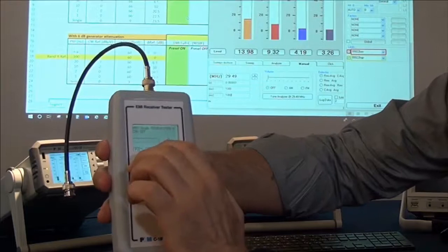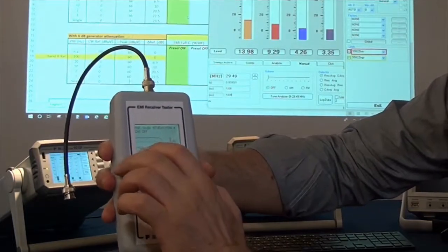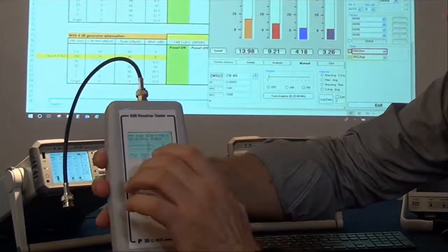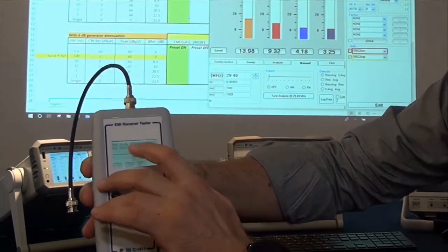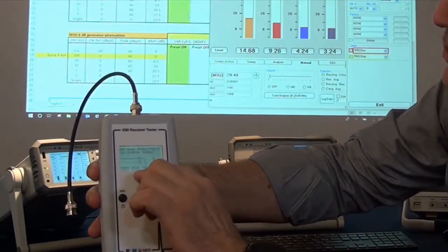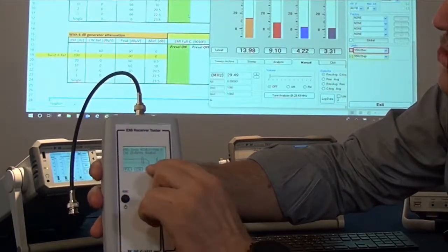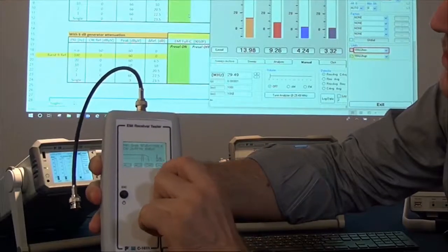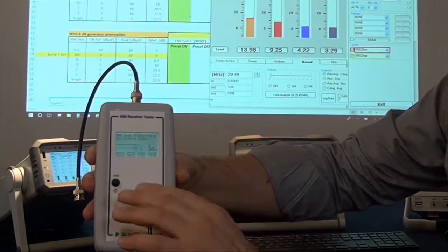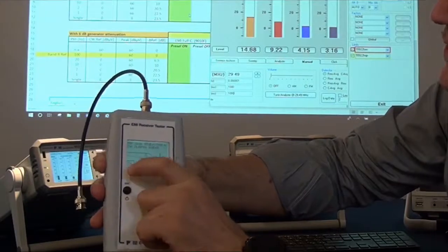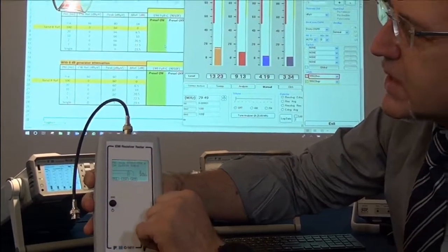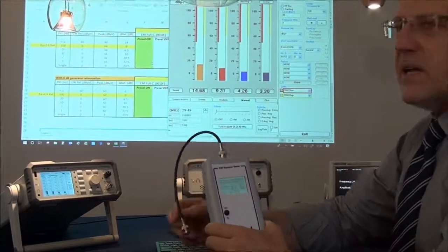So that's meaning with the carrier wave we can start just checking about the signal that we are able to measure, and we will use the frequency that is 29.49 MHz, so it's very close to the end of the B band. In this case we better use the attenuation for only the carrier wave by 20 dB, so we can stay in the range of the spectrum analyzer that is having a maximum level of 100 dB microvolt it can measure.